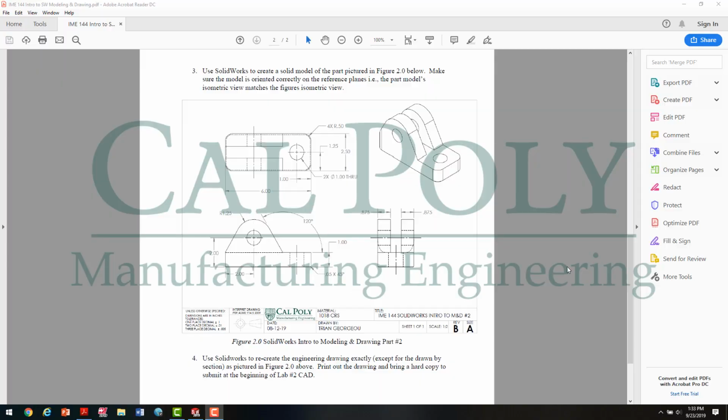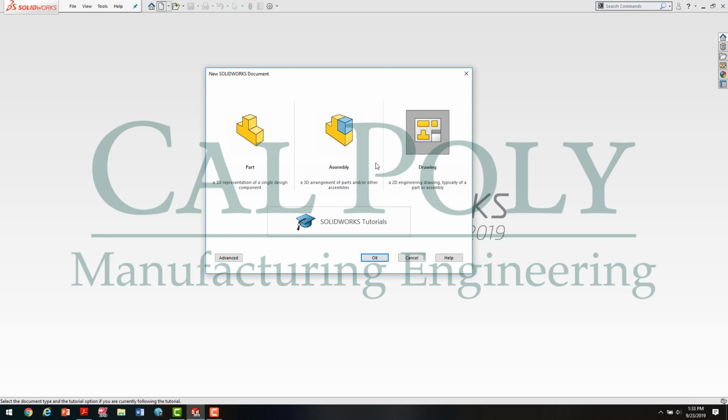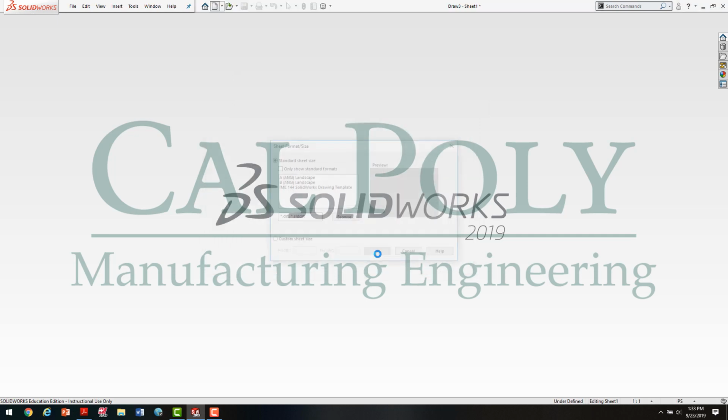In this video, I'm going to show you how to create the engineering drawing for part number 2 on your IME 144 SolidWorks Intro to Modeling and Drawing assignment. So we're going to go ahead and create this drawing that you see right here on the screen. To do so, we're first going to go to SolidWorks. We're going to go File, New, and we're going to select Drawing.